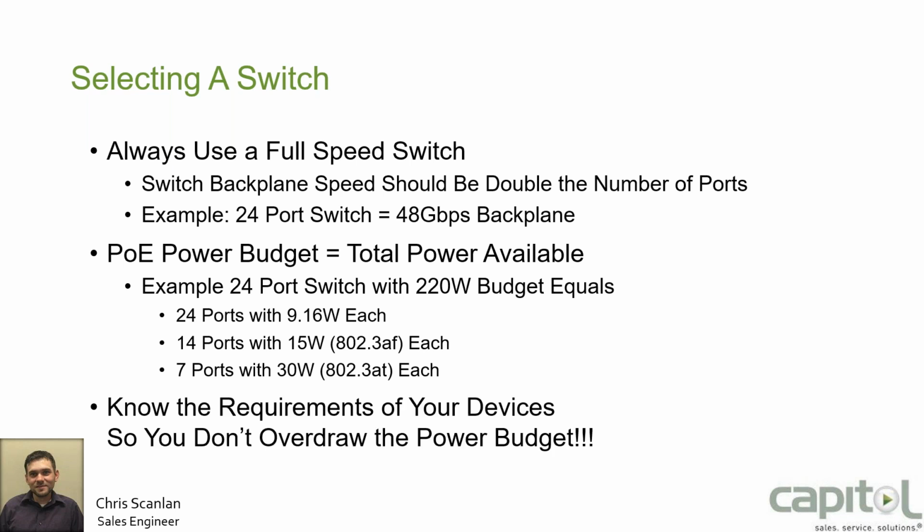So you really want to make sure that you know the requirements of your devices. If they're cameras, if they're access points, if they're keypads on the walls, whatever it is that you're powering, you want to make sure you know how much power they're going to take, because you don't want to burn your switch out or not be able to supply enough power to them. Okay.